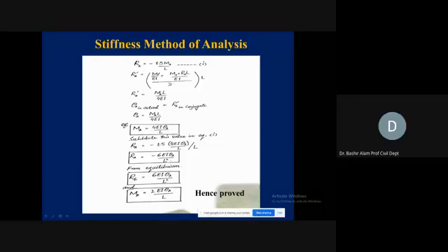Now from equilibrium, RB will be equal to 6 EI theta. You can put these numbers now. So from equilibrium, you can find out summation of vertical forces. And then MB very easily you can find out because you have RA, you have MA, you can take moment about B. So MB will be equal to 2 EI theta A divided by L. Plus sign means it is in the same direction as that of MA. So we put all the 4 now.